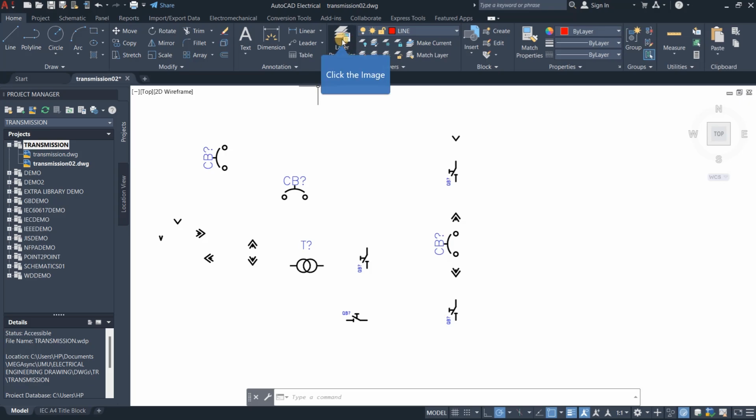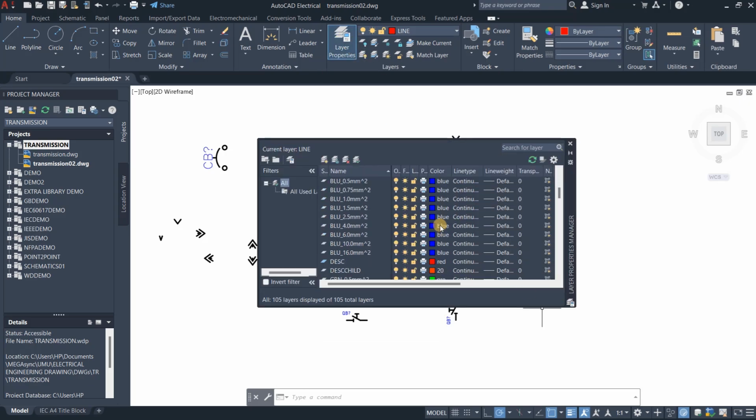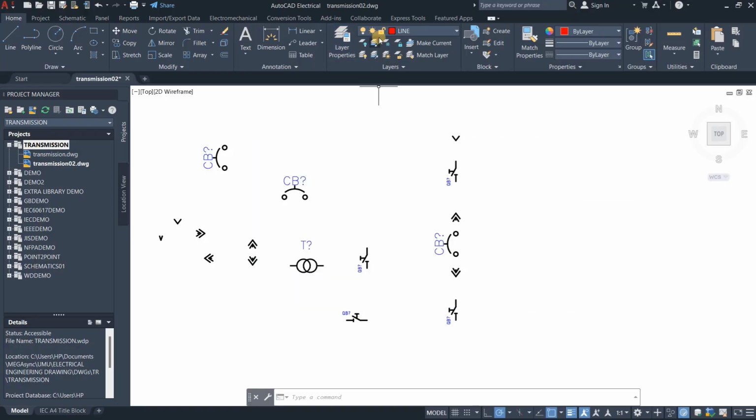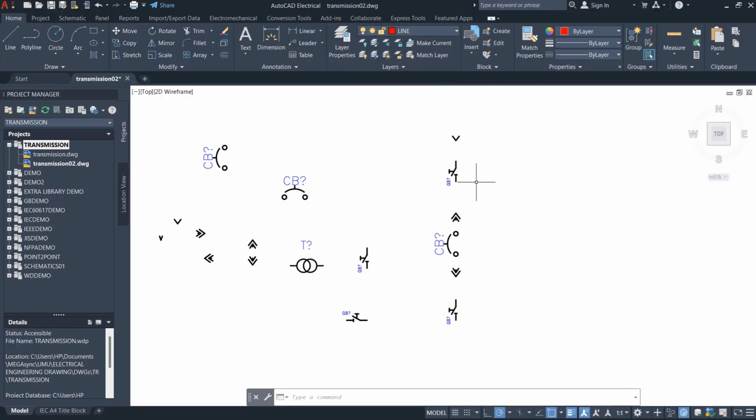So I created an additional layer. I called it line. It's over here. I created a layer, I called it line, gave it a red color, a little bit of line weight, 0.05 millimeters. So you come here and make sure line is active. So that's the one which is active.